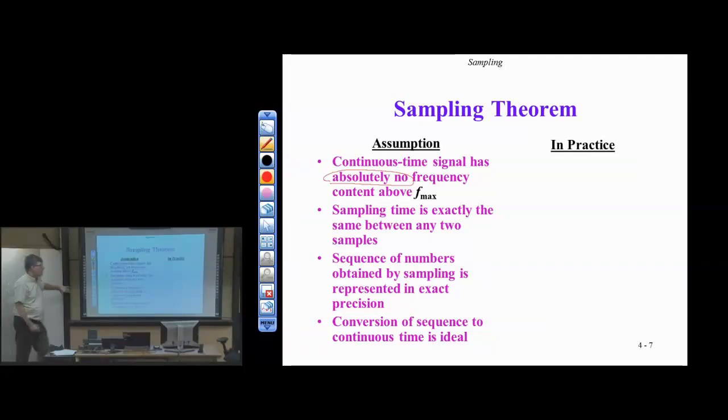How do we deal with it? So we got noise, so not met because of noise. And then how do we deal with it? Yeah, a filter. So not met at least due to thermal noise, and then we can control, again, we can't filter out all frequencies above f max, but we certainly can control the amount of filtering.